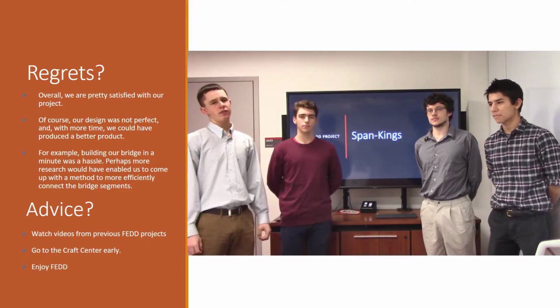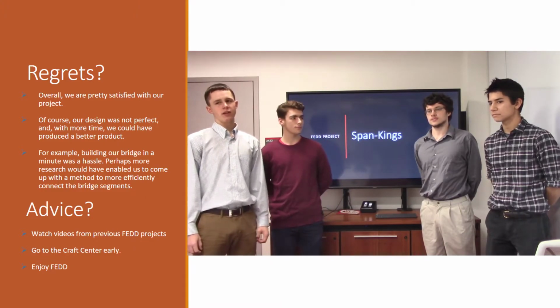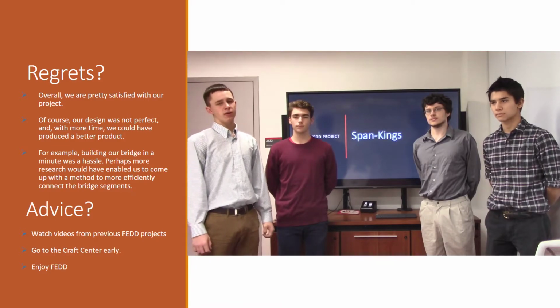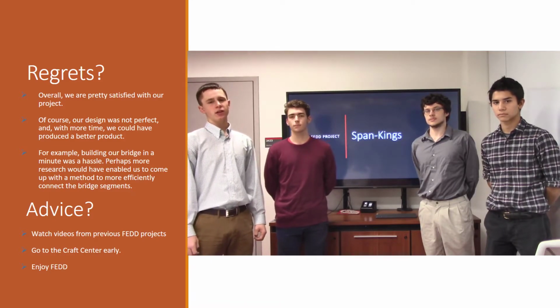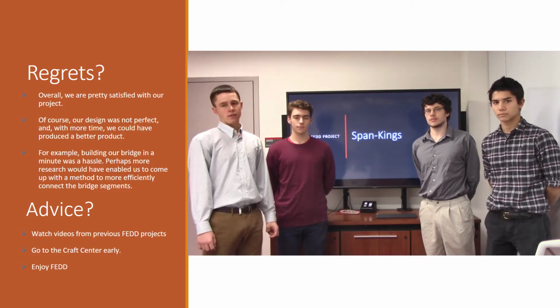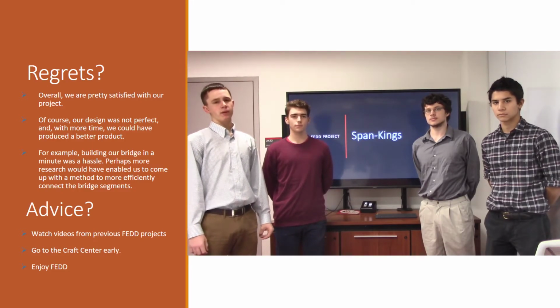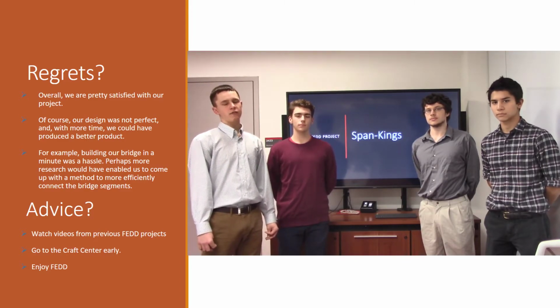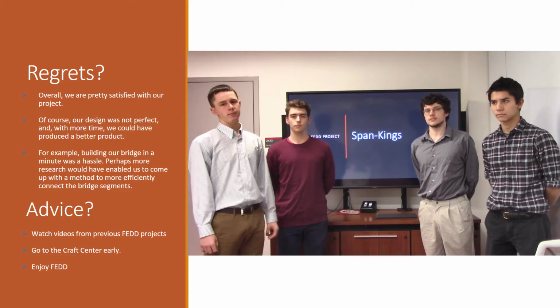In addition, we could have created a thin metal sheath to cover the area of the bridge where the hooks would be applying weight. We noticed that when the weight was being applied, the hooks were digging into the bridge and causing some significant damage. The metal sheath would have served the purpose of distributing the pressure that the hooks applied across the bridge, and therefore we would possibly be able to hold more weight.